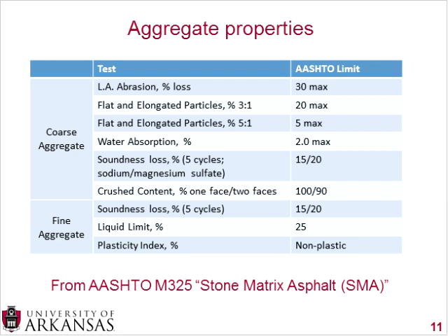On the other side, you do want to make sure that your fine aggregate is behaving. You don't want any fine aggregate that would cause problems with the asphalt mastic portion, the asphalt mortar portion. So for the fine aggregate, you also run the soundness loss, with the same specification as the coarse aggregate, but you also have your liquid limit and your plasticity index.